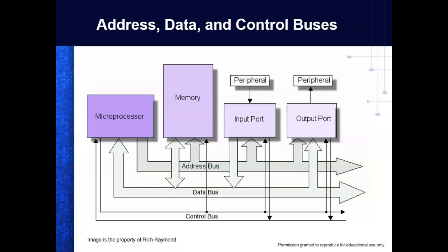So these electronic circuits, the address decoders, that's all they're doing. They're just sitting there looking at the address bus, and when one sees its address come out on the address bus, it's going to select one device. So the mail person only does what? One mailbox at a time. And so it's got the address decoder up here, but in actuality, the address decoder would be in here. You understand that? Now, once we select a device, we communicate. So the address bus is what we call a unidirectional bus. It's one direction. It comes out of the processor and goes out through the whole system.